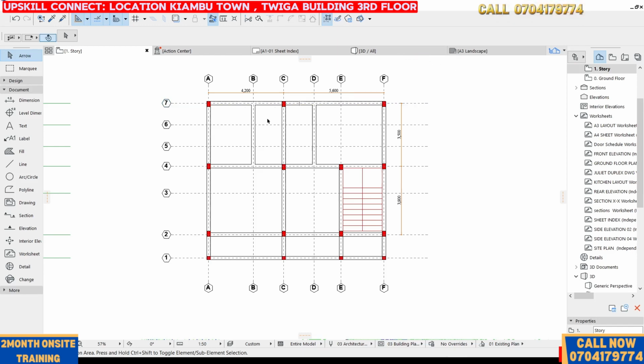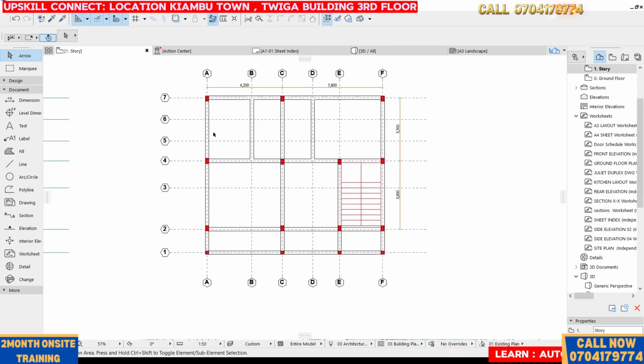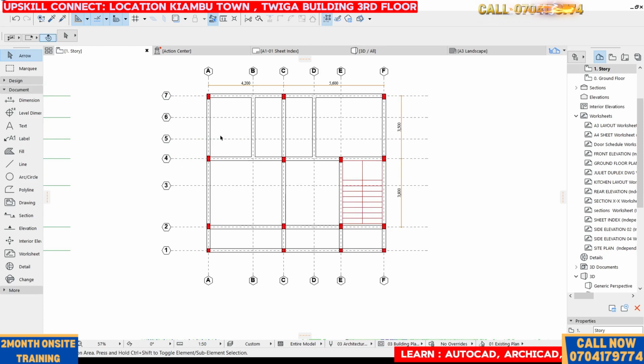Most of the time we name beams based on the grid lines, so you can just use alpha, any kind of method that you want, as long as they are consistent throughout the plan. So you can say this is beam 1, beam 2, beam 3, beam 4, or beams which are similar, you name them like that. You can say all the beams are similar, but because we have different grid lines, you can say probably they are different because of the position and everything.